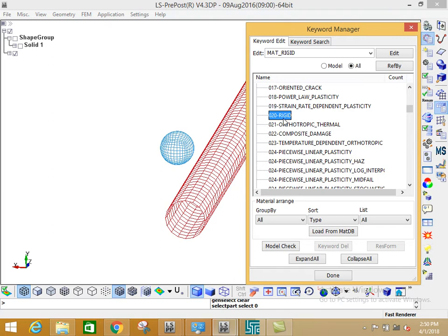Right now we have the pipeline, and we assume some rock hits or falls on the pipeline, so it will bend like this. What is our interest? We want to study the pipeline. We don't want to study how the rock is destroyed, right? That's why in this problem we can set the rock to be rigid, because in real life the rock will smash the pipeline very strongly, and maybe the rock will break down. But we're not interested in the rock. We want to study the pipeline. That's why we can simplify and say the rock is rigid.